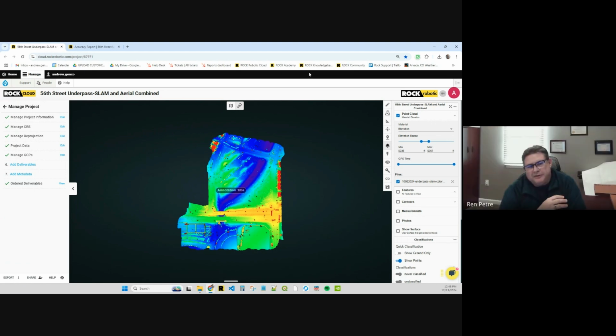Yeah, I'm a little leery about trying to load it into the actual drone, the GPS, and have everything auto corrected at the same time. Sometimes I feel just let it do its thing. The base is set. As long as that's not moving, everything is oriented to that. And then I can always shift it later, because I've tried to set the base on an actual known point, but we're usually collecting the points at the same time. And I'm still going to end up adjusting it, whether it's tenths or feet. So I usually just let it do its own thing, let it sit. Then when we come back, we can post-process everything internally and really get it tight that way. That seems to have worked well for me. I haven't really had any hiccups.